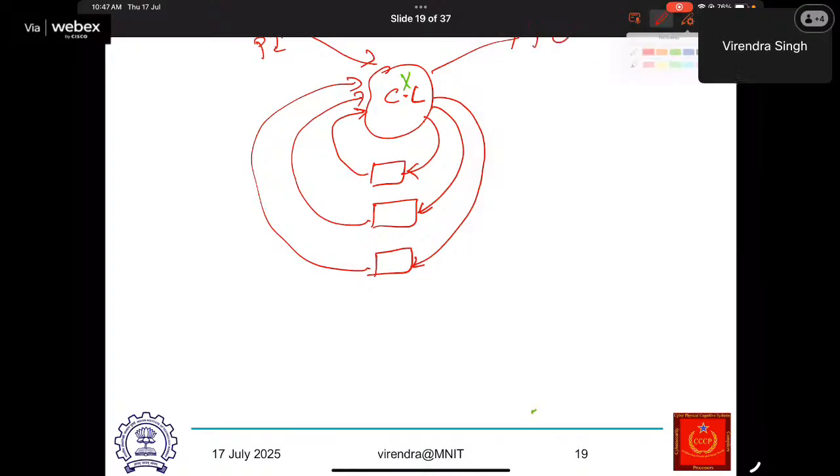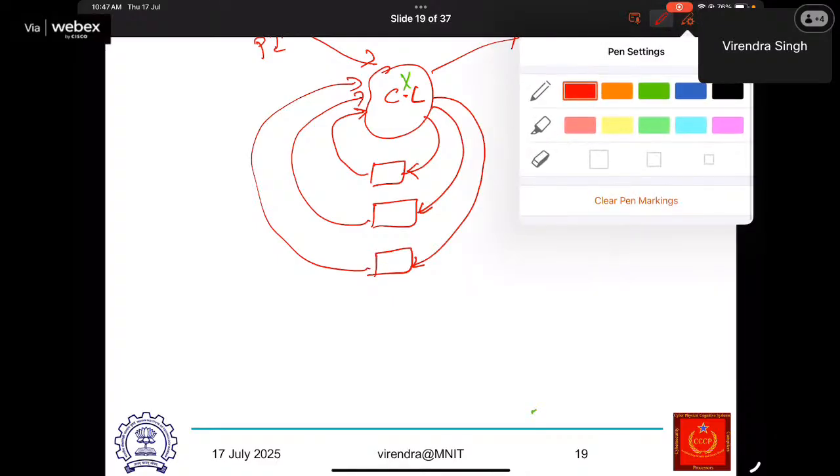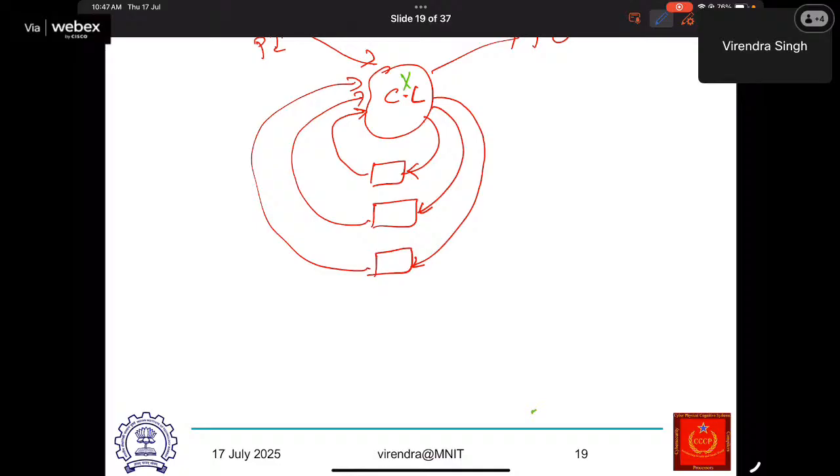Now, how should I treat this circuit? I say that here, consider this as primary input and this as primary output from the combinational ATPG point of view. But at the end, I may need to assign values to these state variables. These state variables may be S0, S1, S2, and I should be able to read them. How can I do that?